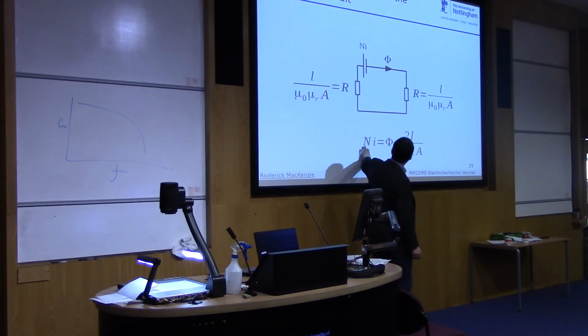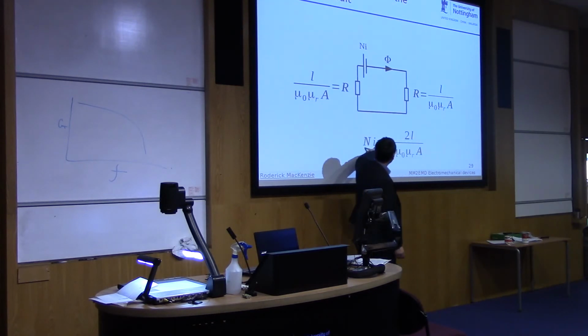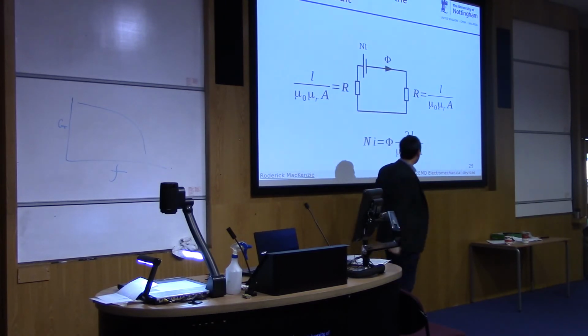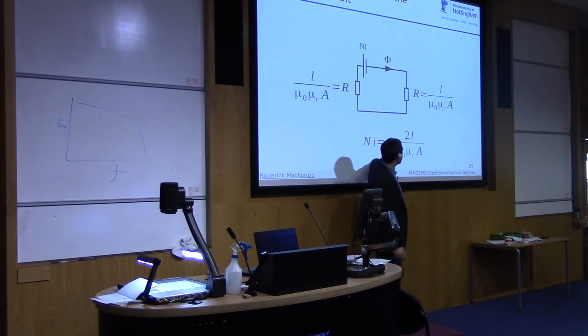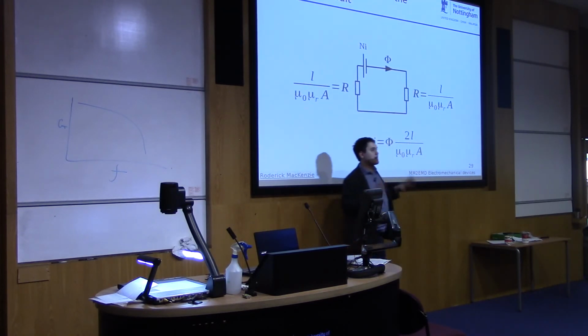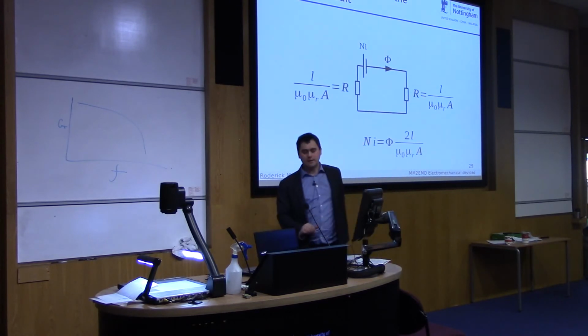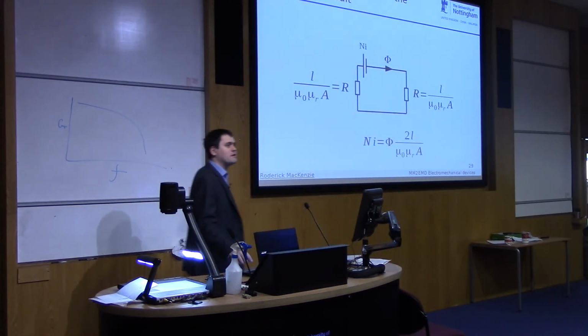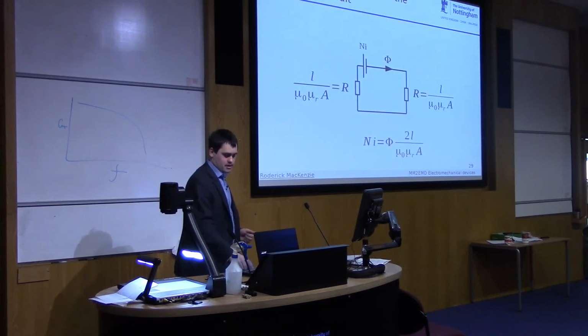Yeah, so now we can write our equation for our magnetic circuit. If this was a normal circuit, you could think of this as V, or the driving force, because it's the magnetic force that's being generated. This is the current, effectively, the I in a normal circuit, and this would be the resistance. So you can think of this as V equals IR, but of course it's magnetic. That's just how I like to think of it. Any questions so far?